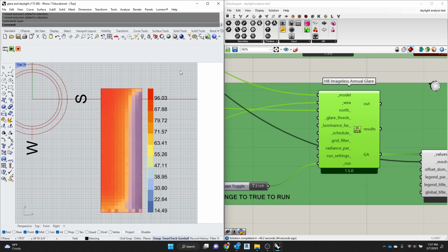So if this was an office space, what's the inverse of 24%? What's 76%? 76% of the time in this spot of the building, you're going to have unbearable glare through the light, and you will be sitting at your desk squinting because you're going to be blasted with light from that side. If you're way back here, you probably have no light, so you're dark, but you never have any glare. So I guess that's the only benefit of sitting back in the corner.